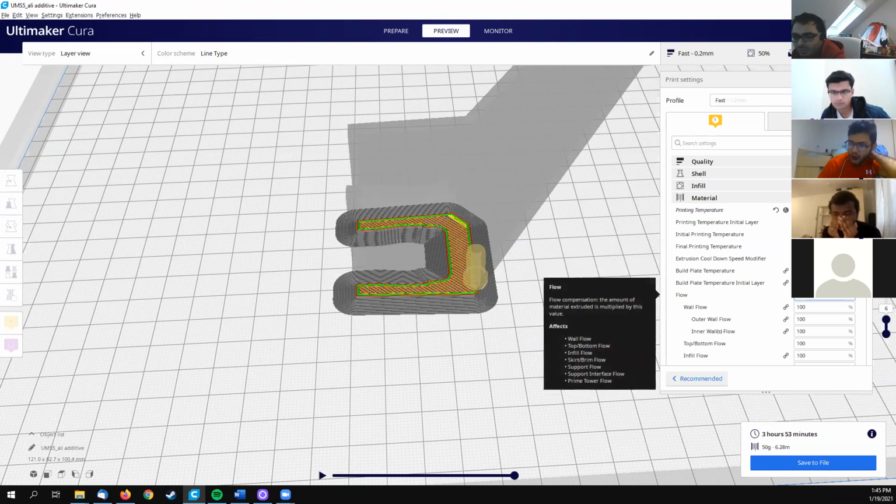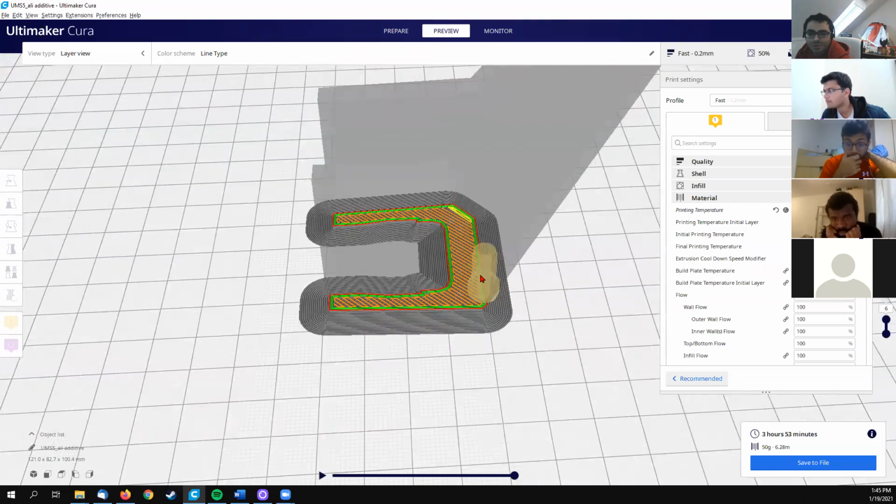You have here an additional very important value, flow, and that means theoretically, the software is calculating how much filament should be pushed into the nozzle to extrude the needed quantity. Theoretically, the world functions perfectly. Practically, the world doesn't. So the filament sometimes has difficulty moving, difficulty flowing, some material diameter is varying, whatever. And sometimes the nozzle, if it's extruding fast, it will cool down, and the heat source in the nozzle will not give it enough heat to extrude properly.